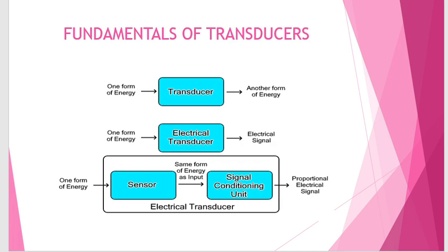As an example, if I talk about the strain gauge, it operates based on the resistive principle. If I talk about the LVDT, then that belongs to the inductive phenomenon. Like this, there are different types of sensors which operate under the capacitive effect. For example, a dielectric based transducer will operate based on the capacitive phenomenon. So these are the fundamental things you need to know regarding transducers.